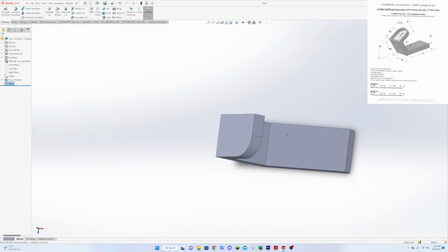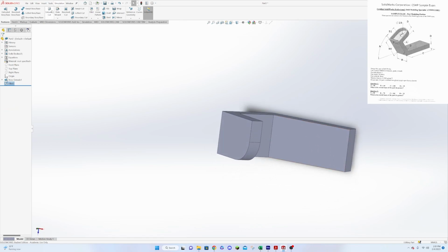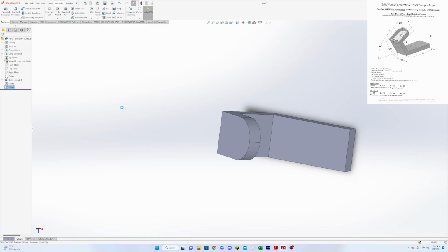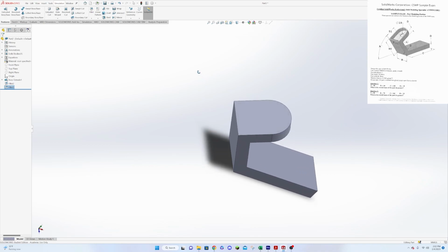And then if we go over to this line, we can do another fillet, and we can do the same thing. It autofills with that 32, but you want to make sure that you change that to your global variable. Because if you don't, when we update our global variables for the second part of this, you'll notice that the numbers don't work out right. And so then if we say enter and say okay, now we get a rounded off edge there. So that's pretty simple and works pretty well.